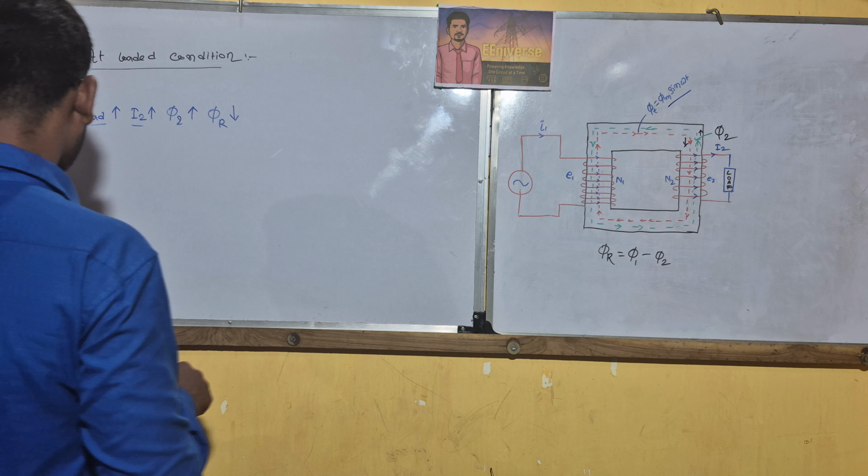If the V by F ratio is constant in our supply, then the main flux will not change in the transformer.